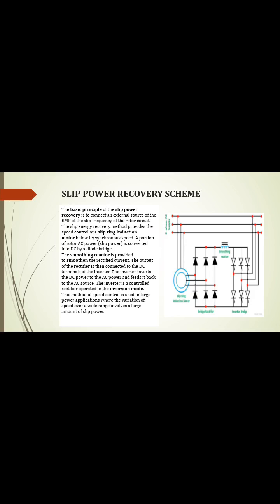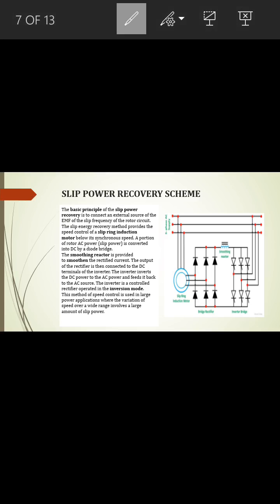Slip power recovery scheme. The basic principle of slip power recovery is to connect an external source of EMF of the slip frequency to the rotor circuit. And the slip energy recovery method provides speed control of a slip ring induction motor below its synchronous speed.